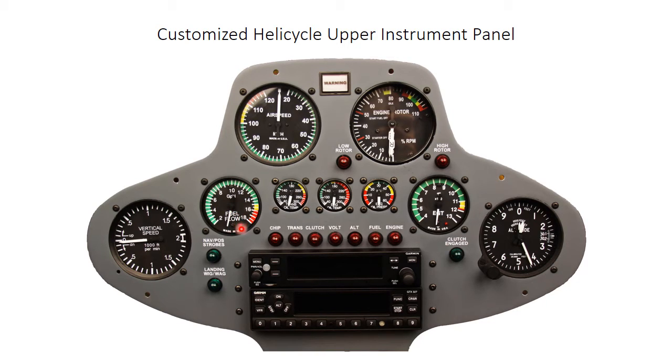I don't know if you can see them, but there's one right here for the fuel flow, and there's one right here for EGT. The smaller indicators, these 1 1/4 inch diameter ones, are not large enough to have an internal LED, but they all have alarm outputs that go to my CAS board.